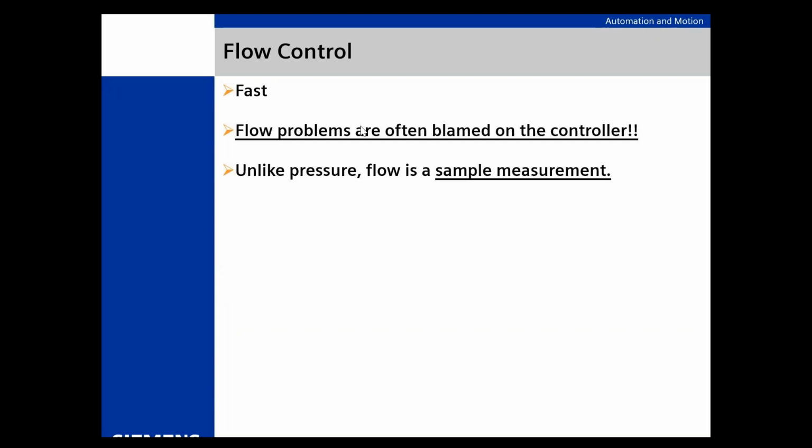People write books on flow. Maybe this is not as accurate as I think it is. I've got a slurry and it's dragging on the pipe boundary. That's non-Newtonian flow. That could be way off. Well, I'm giving that signal to my controller, and it doesn't know it's off. It's assuming this is all right. Well, what can you expect out of your control then? You're asking for problems. Again, know what's in the field.